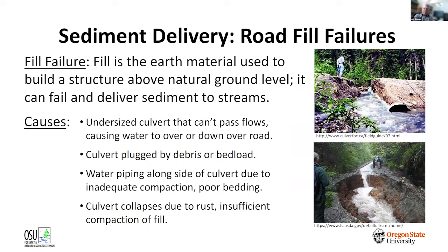Okay, so we talked a little bit about the sidecast roads, but road fills in general can be hazardous, are in fact hazardous locations. When you have roads crossing streams, typically you have some sort of culvert to convey that water from the upstream side of the road to the downstream side. And then you may have fill material in that crossing to create a level road surface. These fills can range from a small amount, 5 or 6 feet. I think probably the tallest fill I've seen over a culvert has been about 80 feet of fill, and that in fact became a safety of dams issue.